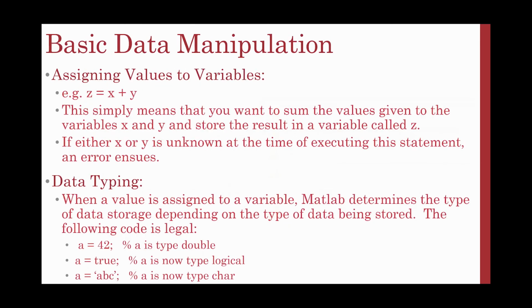So, basic data manipulation in MATLAB. You're assigning values to variables. For example, if I type in z is equal to x plus y, it simply means that I want to sum the values given to the variables x and y and store the result in the variable z. So x and y have to be defined before this calculation can occur. If they are not, an error statement is going to occur.